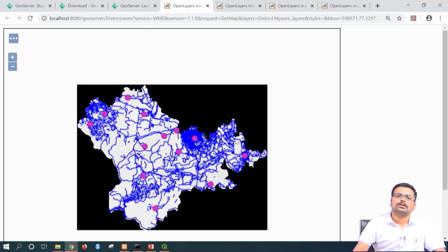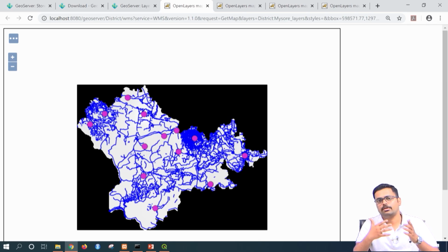Now you can see first there is a raster, on top of the raster there is a road, and on top of the road you have the rainfall.shp, which is the vector. This is how we visualize, and we can take the SLD from QGIS, and finally we can also see how to display multiple layers in Geoserver.